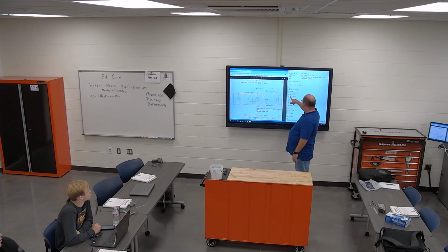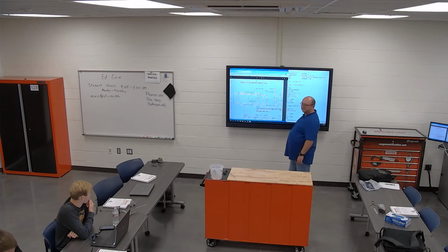Then we're going to do a G01, a Z of 0.1, so now we're 100 thousandths above. That's just so when you're running in single block, it'll stop right there and you can look at it before you plunge into something. Z of negative 0.2, I went 200 thousandths below the material, so it doesn't hang your flute on it.